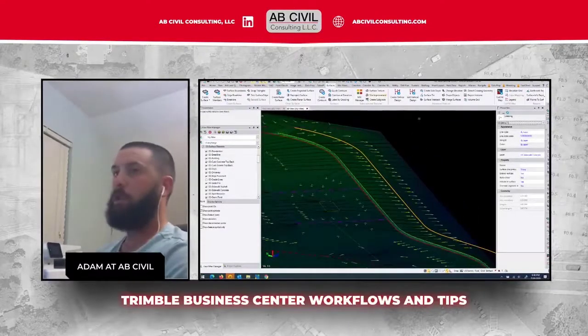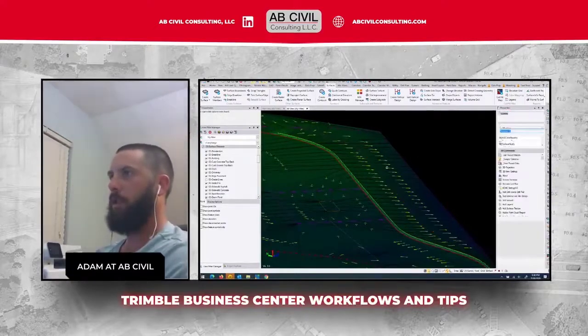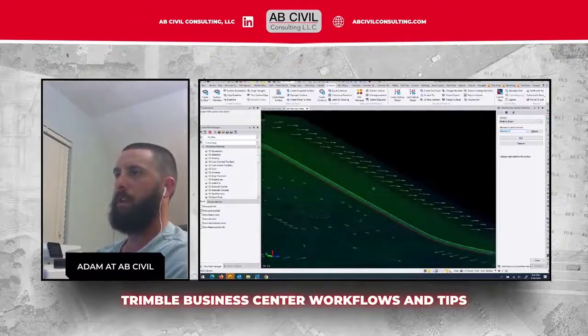So I use surface members so often that I've actually got it as a keyboard shortcut. So for me, it's Control S. My left hand's always on the keyboard. So anytime I just hit Control S, and I've got remove surface member. Just gonna hit add. Now I've got an 8-foot sidewalk.